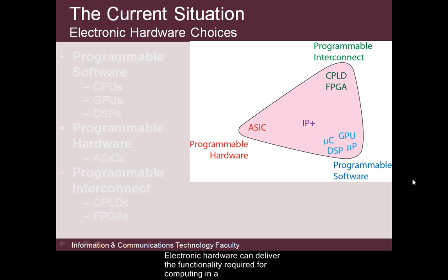The main options from there are in the balance of hardware and software design required to configure the required functionality. Hardware is generally more expensive to design, fault find and update, but it provides a solution with smaller chip area that runs faster and is cheaper to produce in quantity. Software is cheaper and easier to design and flexible to update, but it generally provides solutions that run slower and occupy greater chip area.